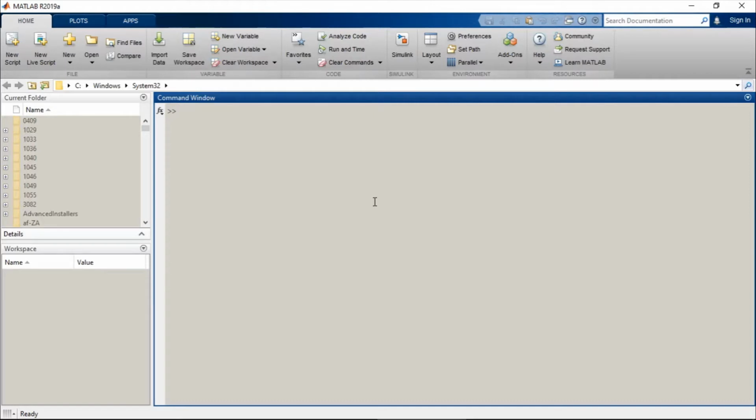In those, the motor torque ratings were about 1,373 Newton meters. I figured this was probably the average pull-up torque, and it didn't really consider the breakdown torque, since I doubt the motors in these cars are used to operate in the breakdown area, because of the slack and everything.